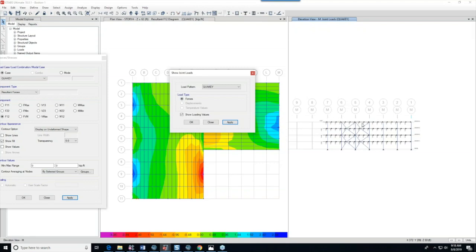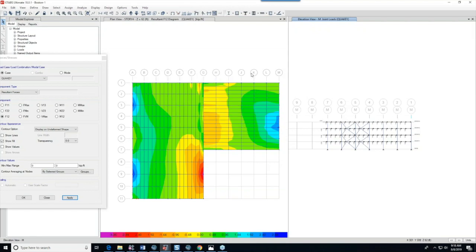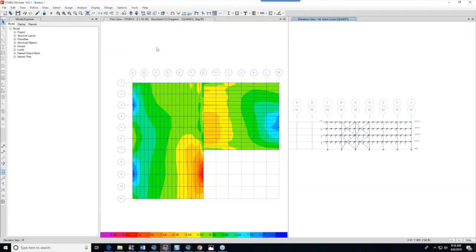And if I were to add up these forces, they add up to about 33 kips, plus the 217 kips coming from the diaphragm equals the 250 kips that's being transferred through the bracing and some load by the columns. So because I've modeled the diaphragm as semi-rigid, I'm able to make these types of determinations about how much shear I have in the diaphragm. And it's just a very handy and useful tool.